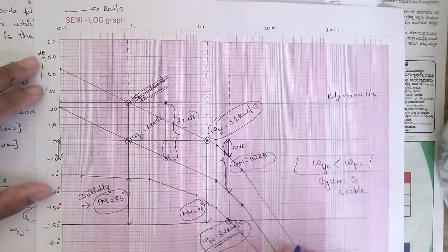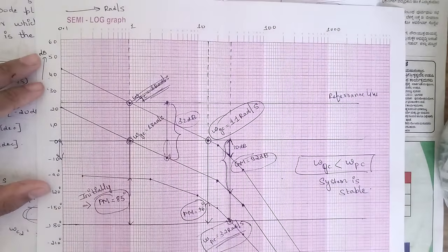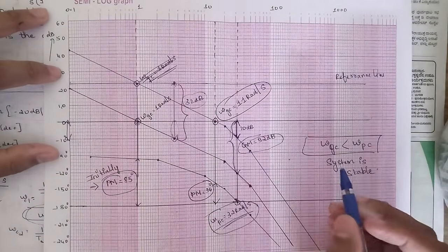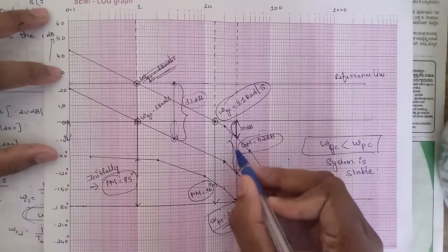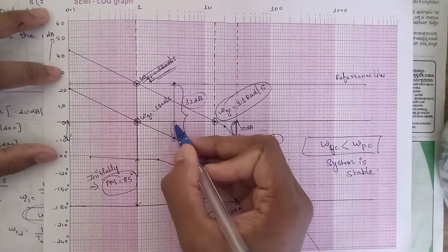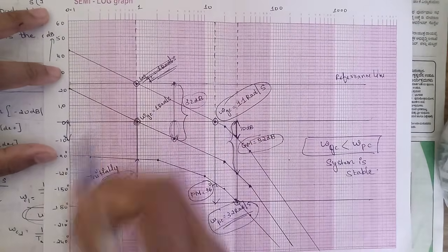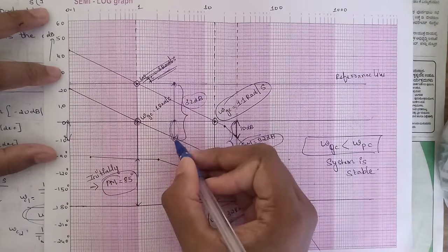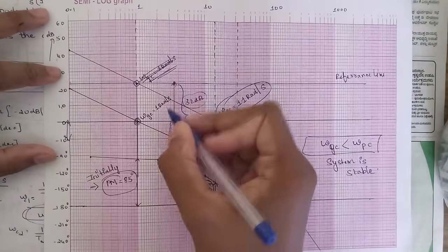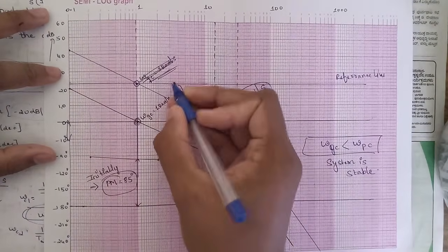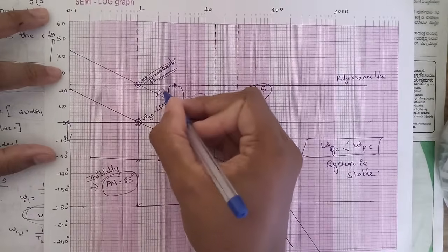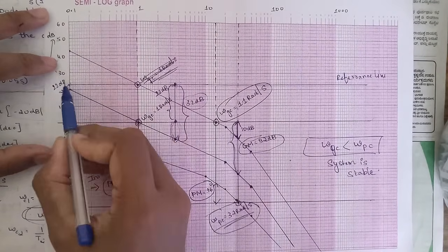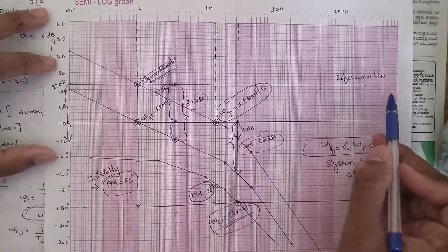Okay, so here you can see this is the new reference line we have got. In the initial gain margin we have got 32 dB, and we have marked a 10 dB gain margin for this magnitude plot, which touches 0 dB and 10 dB here. This is 10 dB, and if we draw a 32 dB gain margin plot here, from 0 up to this point the margin you have got is around 22 dB. So that's why we are drawing a 22 dB reference line. Okay, so this is the 22 dB reference line we have drawn.